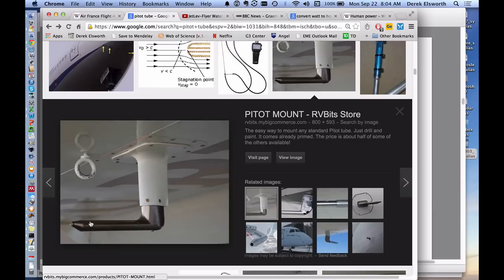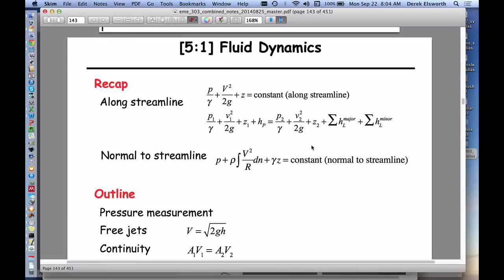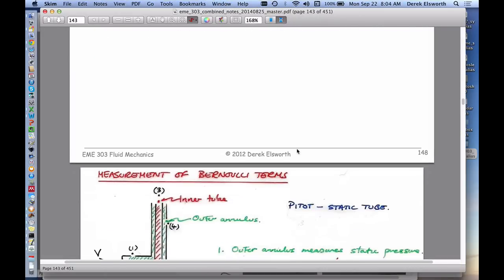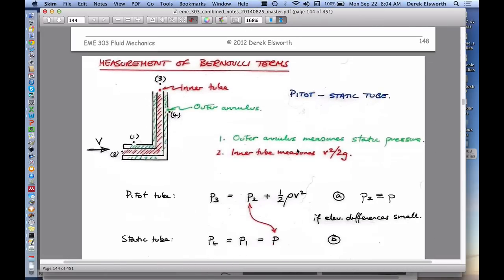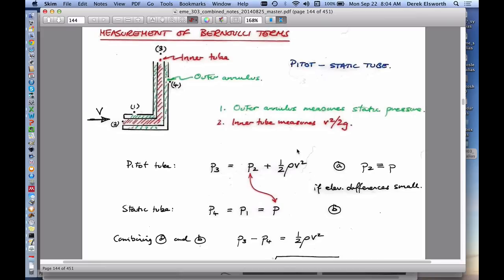And it will also have a double cylinder. It will also have an opening on this side here, which also registers to a different pressure transducer. And by measuring the differences in those pressures, you can say something about the airspeed from the calculations that we did before. Relatively straightforward. And so the geometry of this is very, very simple. This is how it physically looks.